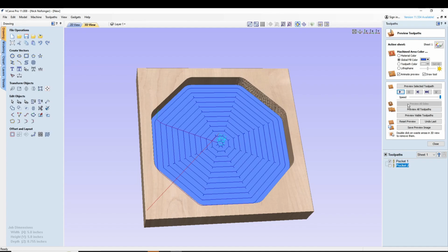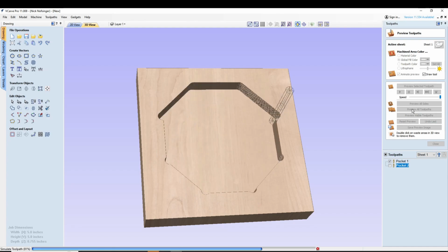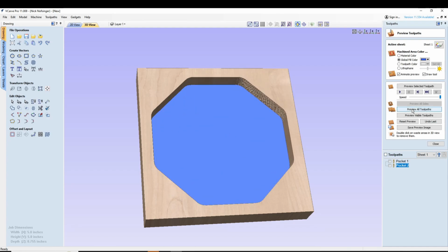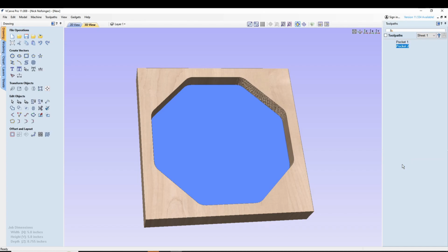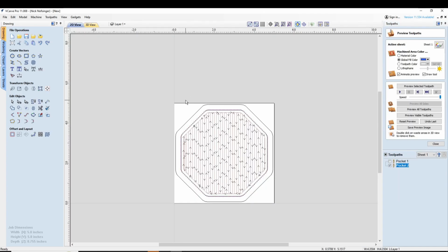And then we have this one here. It's going to come in. So let's go ahead and just preview both these toolpaths. It's going to do that, and then it's going to come in and clean it all up. I need to double check to make sure it is going to do it last pass. Okay. So then now what we're going to do is, since my stock material is 5 inches wide, I'm going to do a lead in.